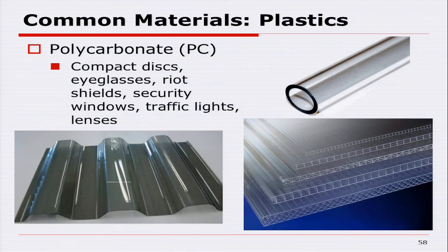Polycarbonate's a higher impact resistant plastic. This is very commonly used in our industry. It's a little bit more pricey. There are some fiber reinforced plastic, fiberglass types of skylights that you can use. If you want to pay double and have a good product, you would probably purchase this polycarbonate instead. We use a lot of this form of polycarbonate on greenhouses, because it is fairly transparent more than being translucent, and it lets a lot of light through.